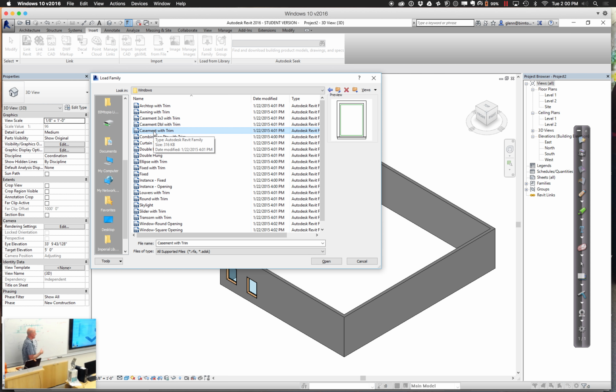A casement window, just in terms of all our funny terminology, casement windows have a hinge on the side and they swing out. Okay? As opposed to an awning window. An awning window has a hinge at the top and it swings up. Okay, so one of those. Double hung windows are the ones where you have the two different panes and one slides past the other in a vertical direction. And the other kind is called a slider. A slider is two panes side by side. And they do that. So they're all just different variations on that.